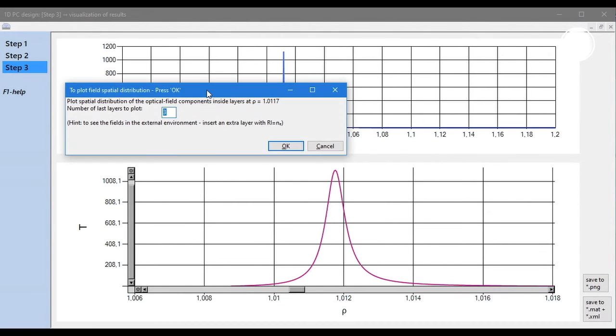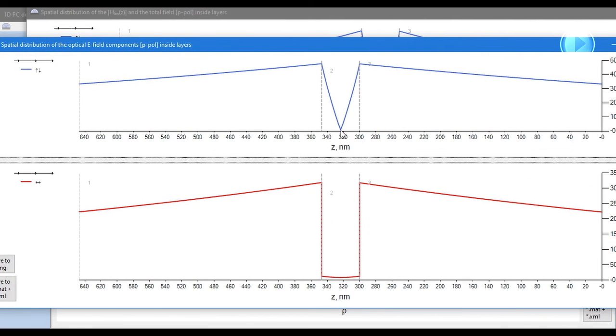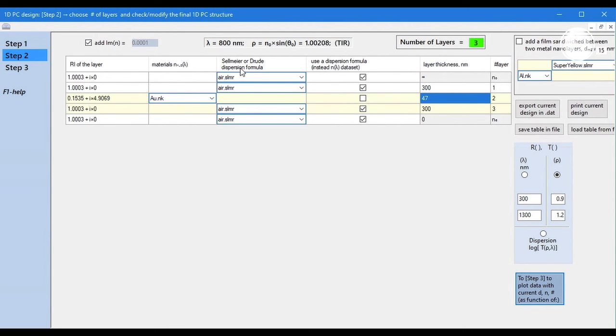This is achieved due to the fact that the structure becomes symmetrical and now we have zero tangential field component inside the metal film. As a result, the attenuation in the metal film becomes smaller and the wave propagates over long distances. But it is clear that it is technologically more difficult to implement such a structure. After all, this is a thin gold film suspended in the air.